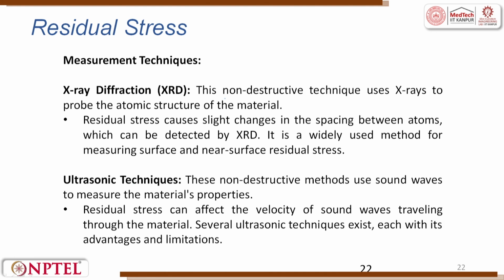In XRD, this is a non-destructive technique wherein we use X-ray. The residual stress causes a slight change. So, what happens is you have an X-ray which hits on the sample and then you collect it by a collector, right. When you collect it, you will get an output, a response like this.